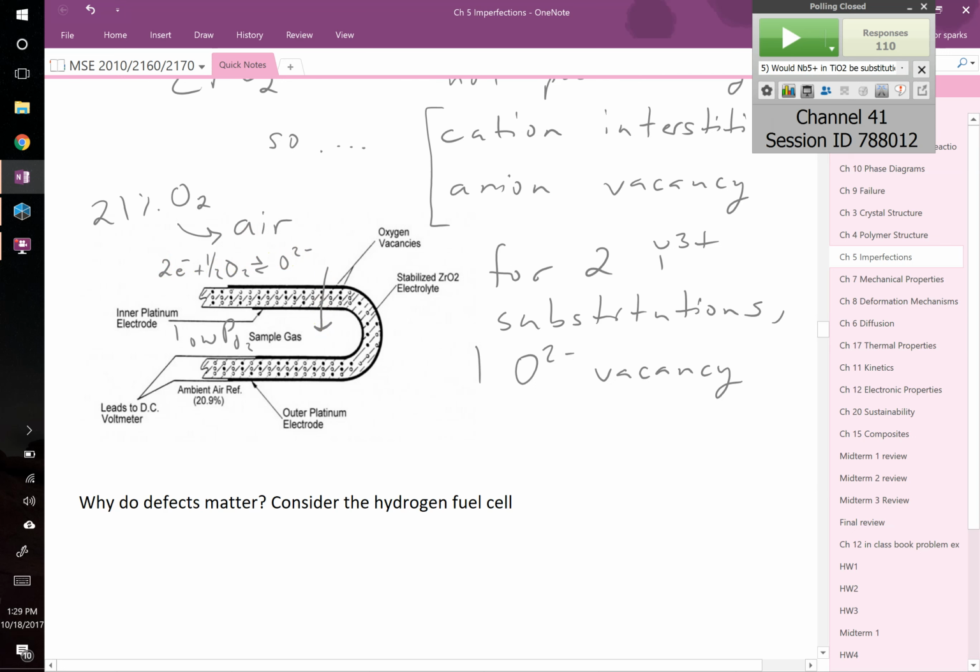And then it travels through your material, and the only reason it can travel through your material is because of those oxygen vacancies, right? If I was an oxygen 2- ion and I wanted to travel through this group of students, if there are empty seats, it's going to be easier for me to step my way through this group. It's hard if it's just pure students, right? If there are empty seats, it's easy for me to travel through. So by doping it with yttrium, you create empty seats for that atom to hop its way through the lattice and get to the other side where it wants to be, because that's the lower concentration.